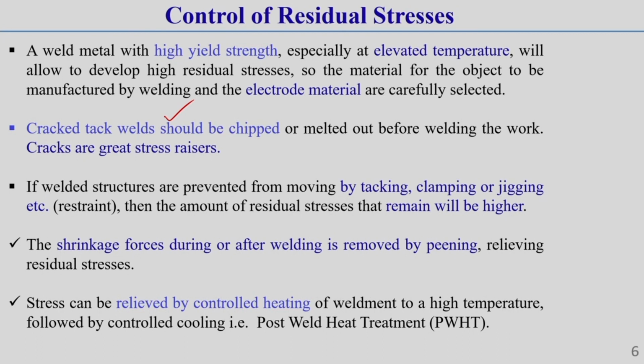If welded structures are prevented from moving by tacking, clamping or jigging operations, then generally the amount of residual stress that remains will be high. These things also you should keep in mind. If we prevent the deformation of the welded structure, that is the restraint effect, then the higher the restraint in a structure, the higher will be the residual stress.